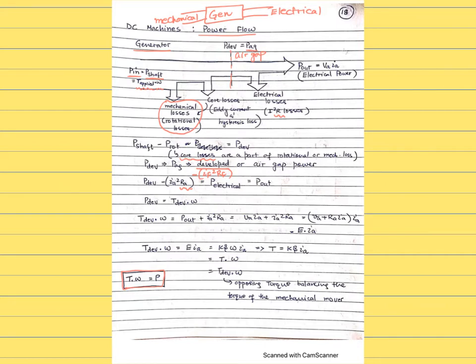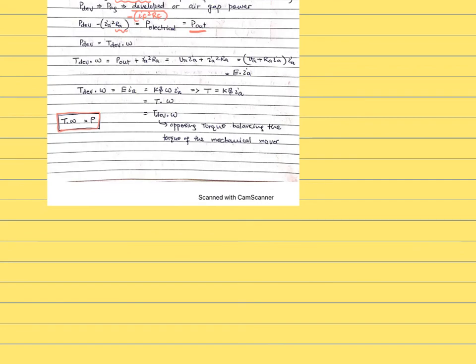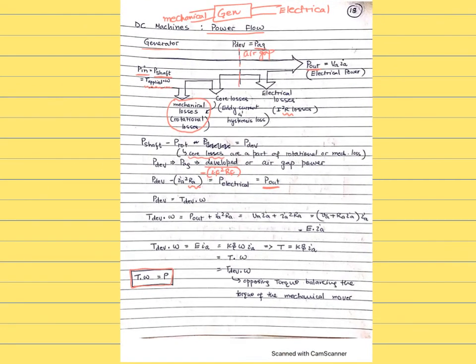Okay, there we are. So we are at the output terminals now. That's your output power, after you took off the electrical losses. So the output power is here, and this is where you are now in the electrical system, the electrical equivalent circuit. This is how your electrical equivalent circuit looked.